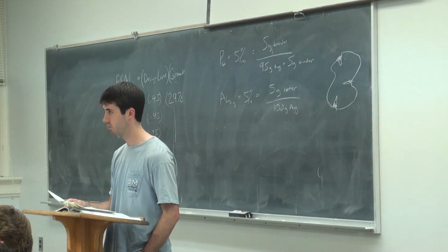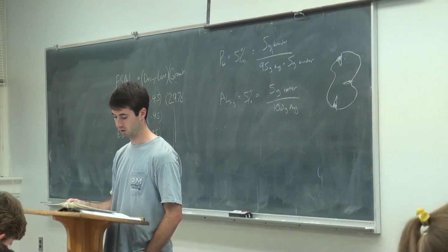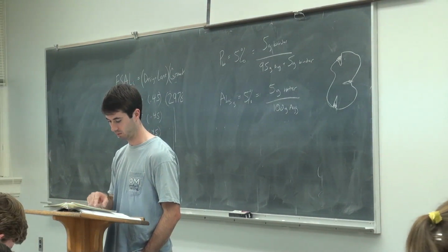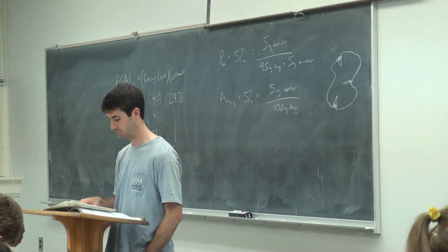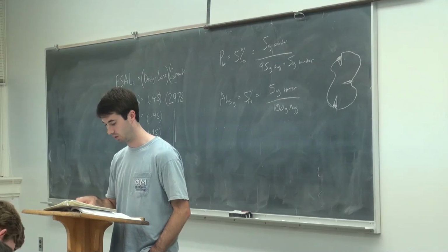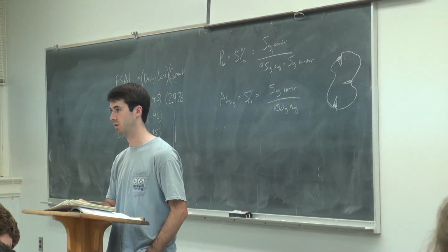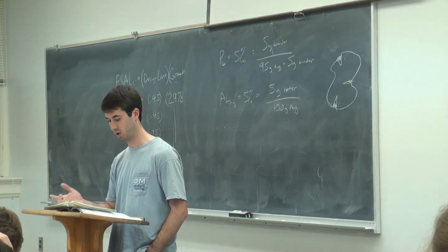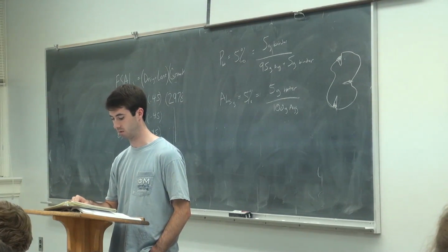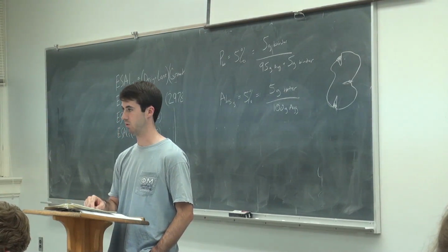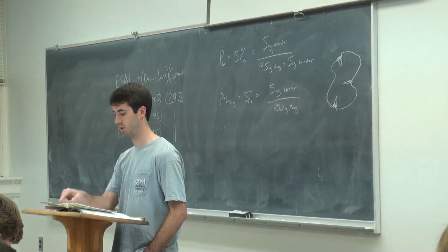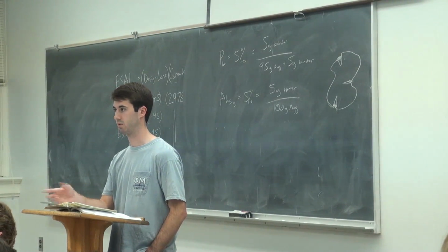Does that make sense? This intermediate temperature, okay, so we said 64-22 would be the -12 on the very low end. The intermediate temperature would also have to pass that 25C. So I said if it failed one of those criteria, if it failed at -12 for creep stiffness or direct tension, it fails across the board for that low temperature for the -22. And you have to do it again.